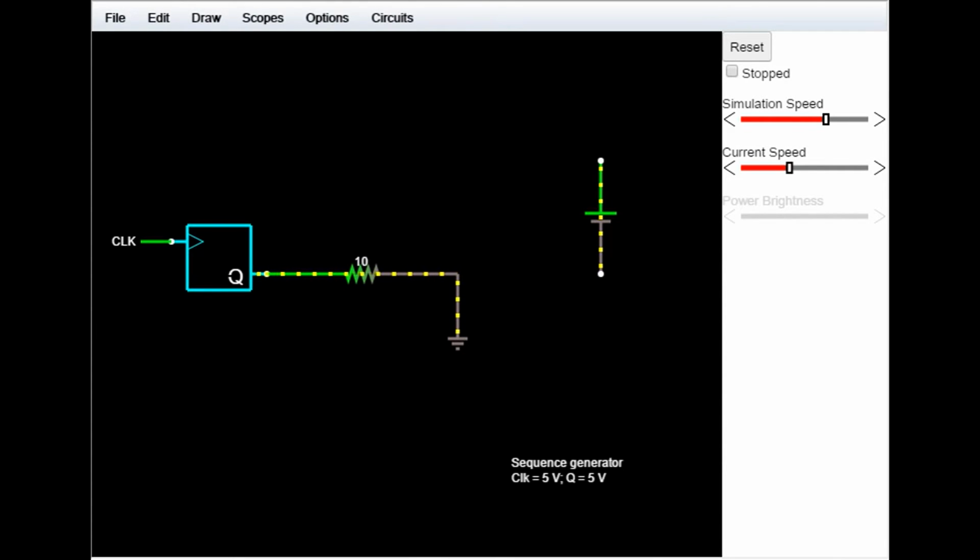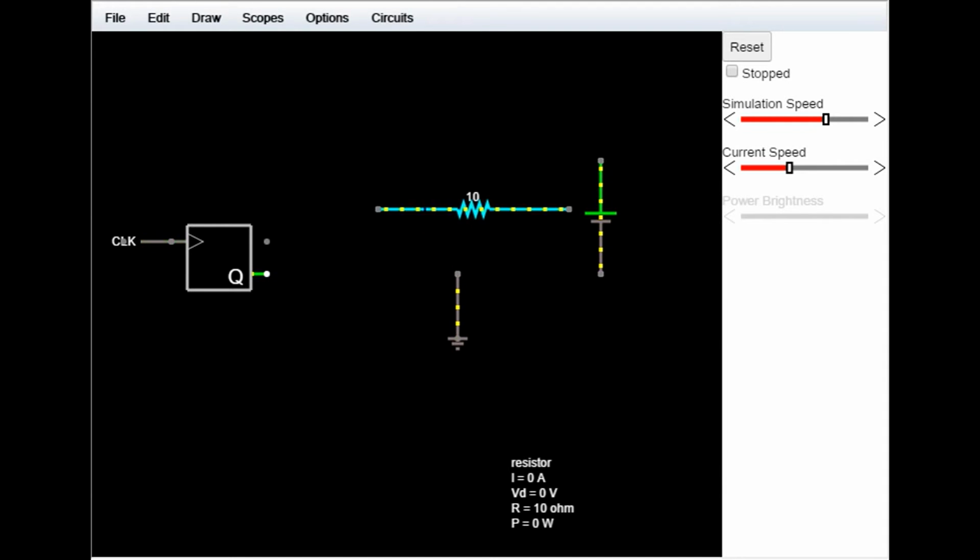The microcontroller is really built out of transistors and diodes and solid state electronics, and 500 milliamps is too much for those transistors in that circuit to drive. So this is a very fast way to burn out a microcontroller by driving half an amp through it. You should never do that. That's a very fast way to burn out a microcontroller.